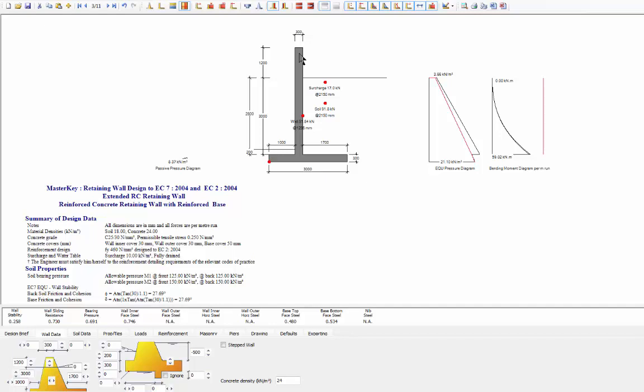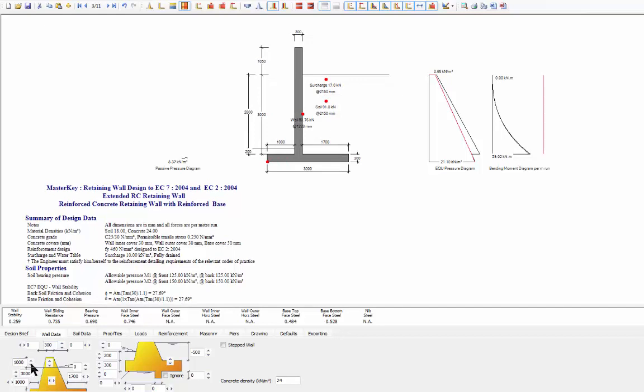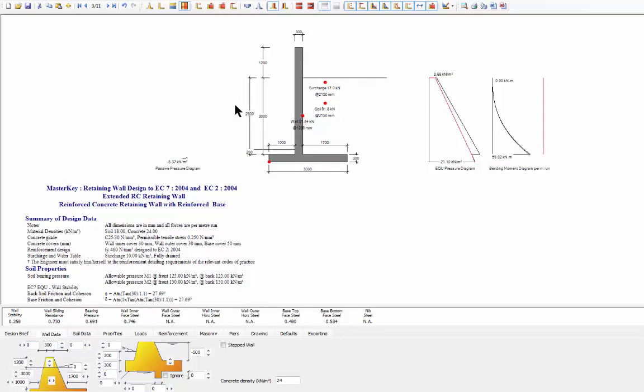in concrete, it will actually be reinforced, and if we export our results, which we will do later on, it will all come through. And the extension is just a separate input here, so I can pull that back down to say a meter if I wanted to, or make it higher. We don't have to have an extension, and we can get additional loading onto the structure, from a fence, from a railing, without putting the extension on, and we will see that later on again.